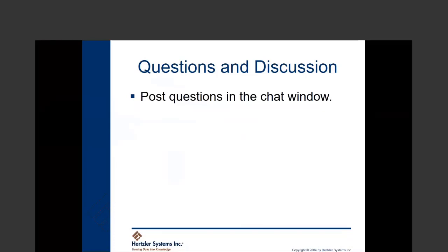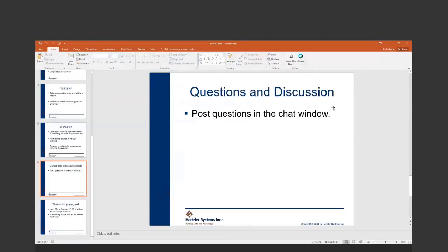Okay, well, what I normally tell customers when I'm talking about this is, first of all, you need to consider your audience. If the operators on the floor have not been trained and do not know what a message of X bar above control, the upper control limit means, and you're not expecting them to take any action, then you probably don't want to turn that alarm on, or you don't want a note to pop up and require them to answer anything, because you're basically just training them to ignore the alarms.